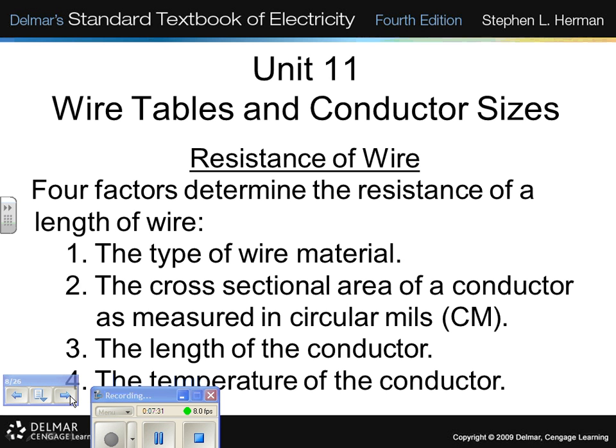Okay? Then you have to do pi r squared for the cross-sectional area of all the wires, add that cross-sectional area up, use no more than a certain percent. Oh, that was right. We're going to talk about that today. And then find out what area conduit you have to accommodate that, to accommodate the proper fill: conduit fill or wireway fill or nipple fill, or let's see, what is the other thing? And whether it's a single conductor, 2 conductor, or 3 conductor. But we're going to talk about that today.